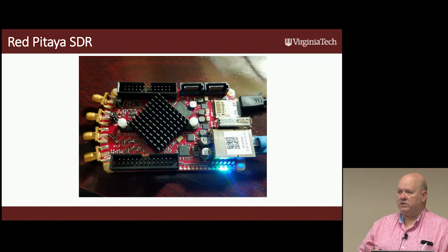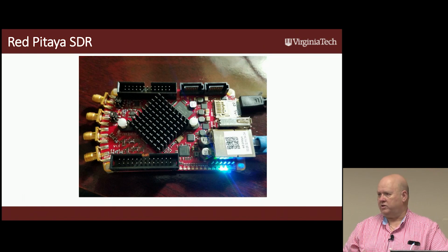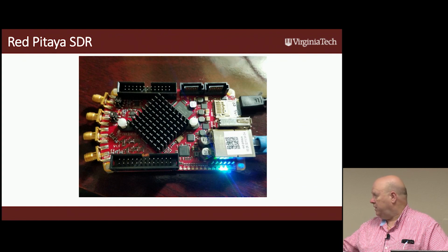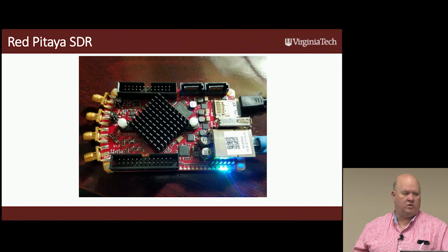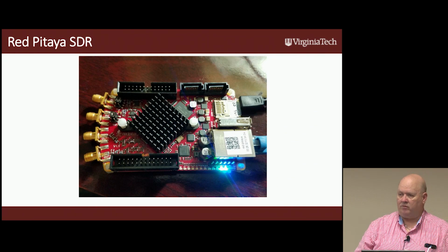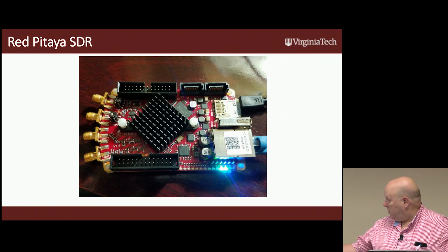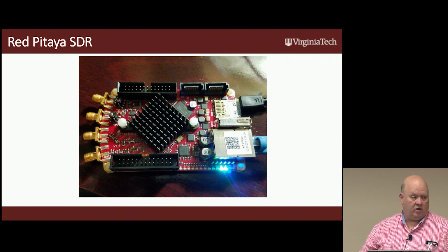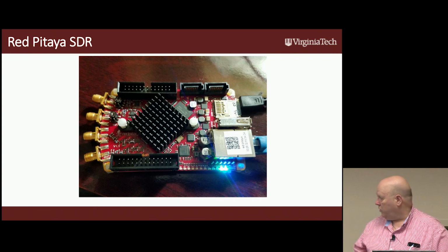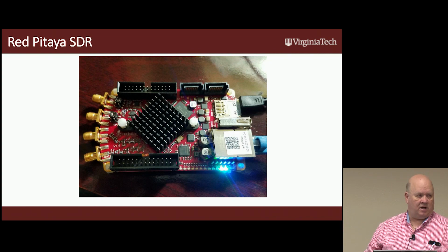So that means, since we're not trying to do any oversampling, undersampling, or overtone work, Nyquist is the top frequency. So this works well up to about 60 megahertz on both transmit and receive. There are 2 receive channels and 2 transmit channels, with gigabit Ethernet to your computer. We want to try to use this for both the ionosonde and the SuperDARN radar software-defined radio, and we'll write all the code in GNU Radio using GRC and hacking on the blocks after they've been emitted.